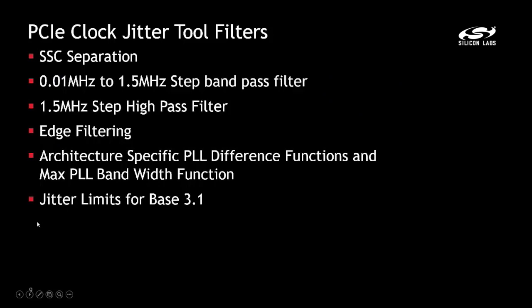PCI Express specifications include and require multiple filtering operations to be performed on the ref clock data in order to obtain the jitter results at the CDR latch.